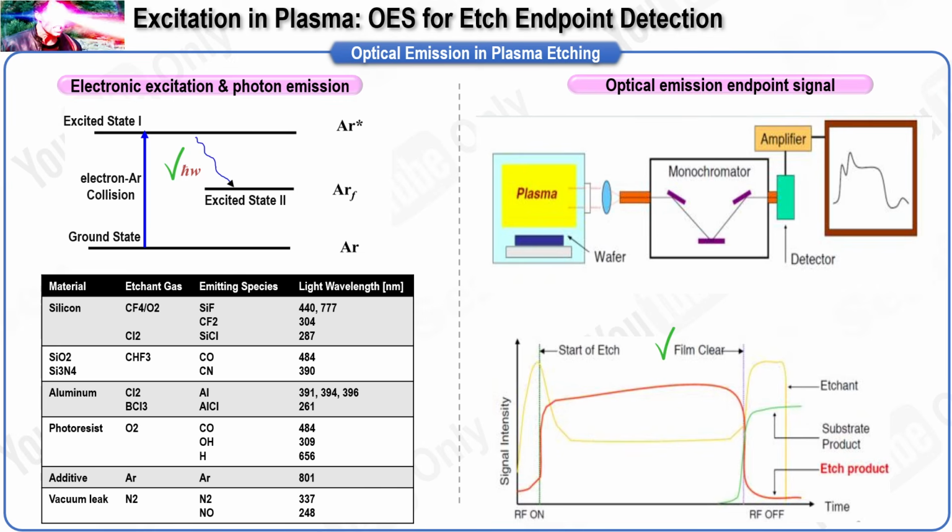and their wavelengths. The variety of light arises from inelastic electron collisions with neutral species. Those collisions also generate electrons, ions, molecules, radicals, and photons, which together form the population of the discharge. Neutral species originate from injected feed gases, from etch products, and from materials released by the chamber walls.